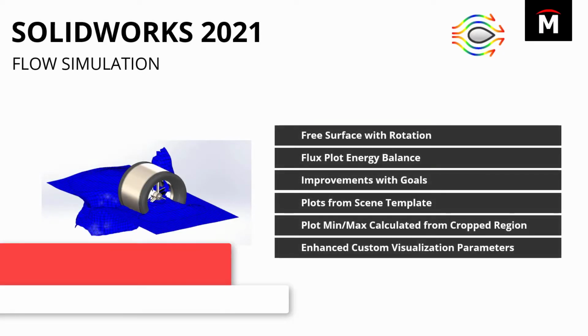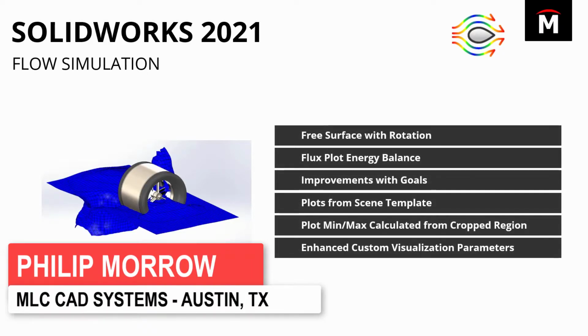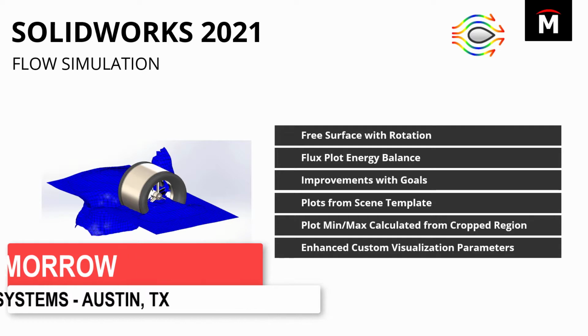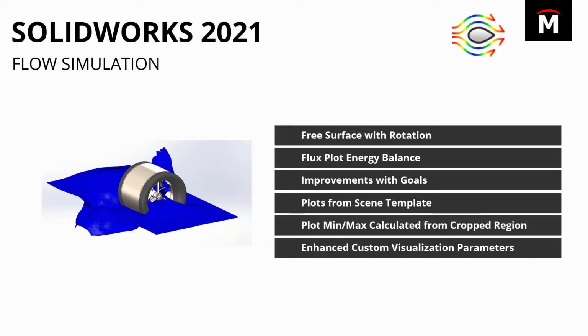Finite element analyses aren't the only simulations we run. I actually spend much more of my time with flow simulation. And every year, the functionality of this tool keeps increasing. With SOLIDWORKS 2021, they actually merged two of my favorite recent enhancements by allowing rotating regions to be combined with the free surface feature. This is ideal for mixing of immiscible fluids like oil and water or propelling a boat across the surface of a lake.